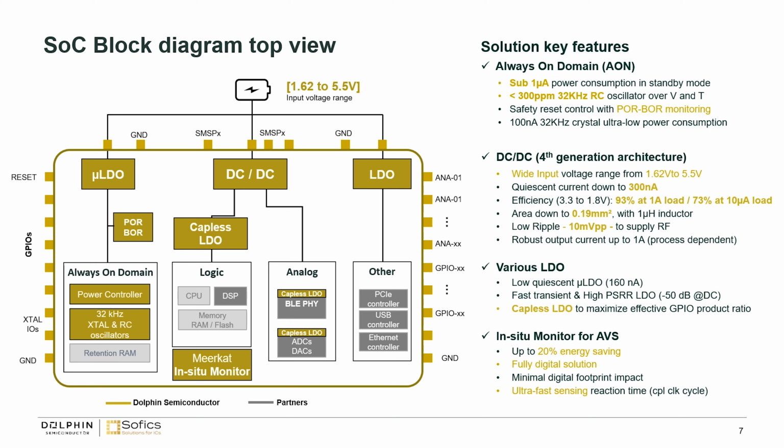As you can see in the same logic block, just below we put what we call Meerkat. Meerkat is one of our IPs, it's an in-situ monitor. And you may say, okay, why do you use this? Actually, it's pretty simple. What we realized is on some computing devices, high computing or energy-care devices, usually there is a lot of guard band or over-design.